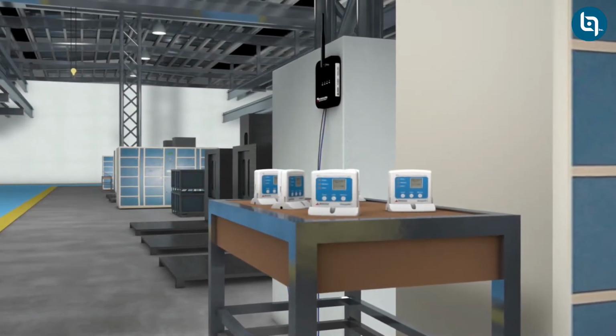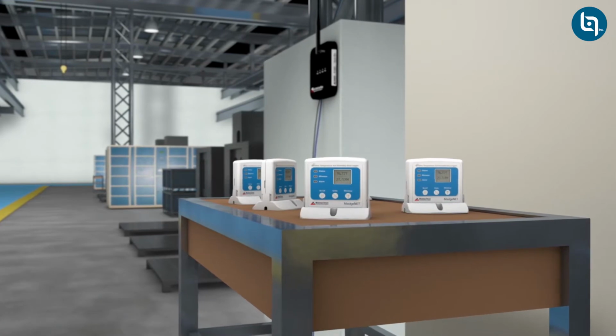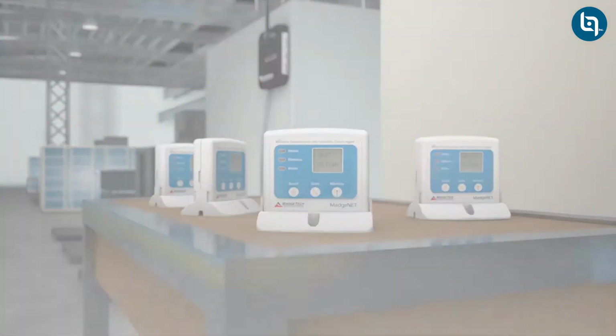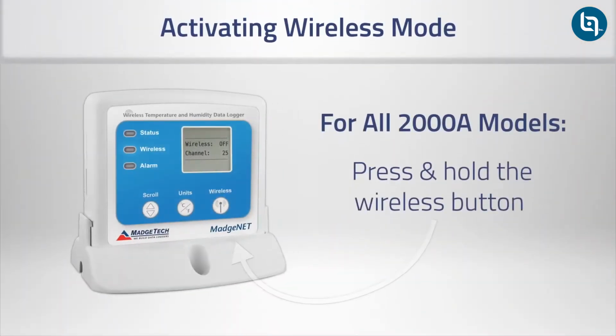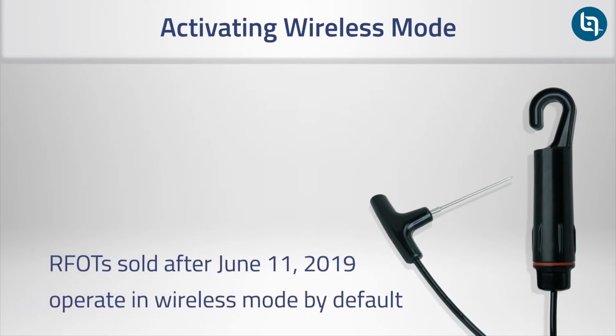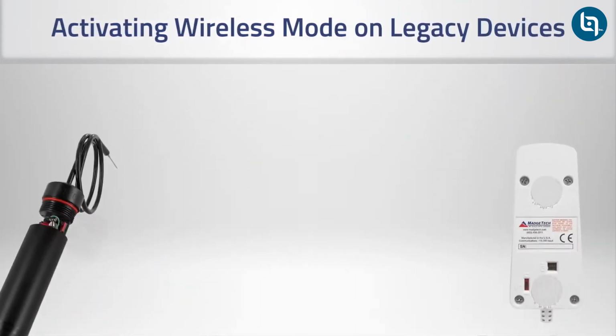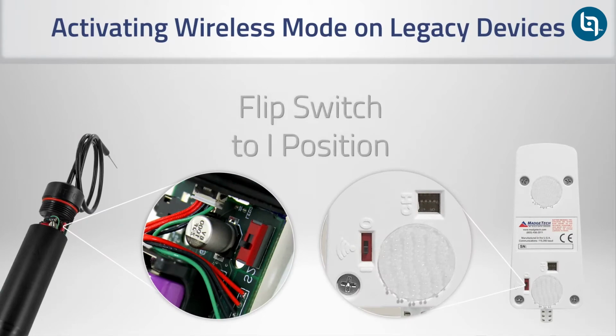Collect all the data loggers that are intended to be connected to the MadgeTech cloud account, and begin the activation process within the near vicinity of the cloud relay. For our 2000A series of data loggers, press the wireless button on the device and hold down for approximately 3 seconds until the logger emits a sound. The LCD should state that wireless mode is on. For RFOT users, the latest generation models are automatically operating in wireless mode, unless connected to a USB. For all other wireless devices, locate the wireless switch and flip it on.